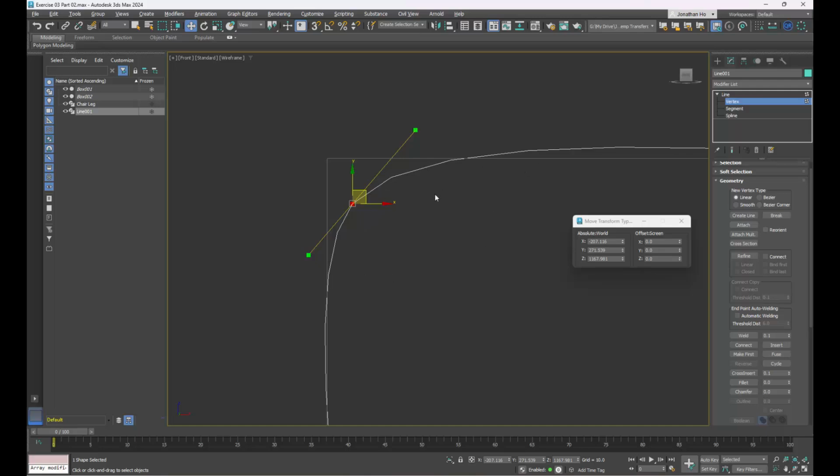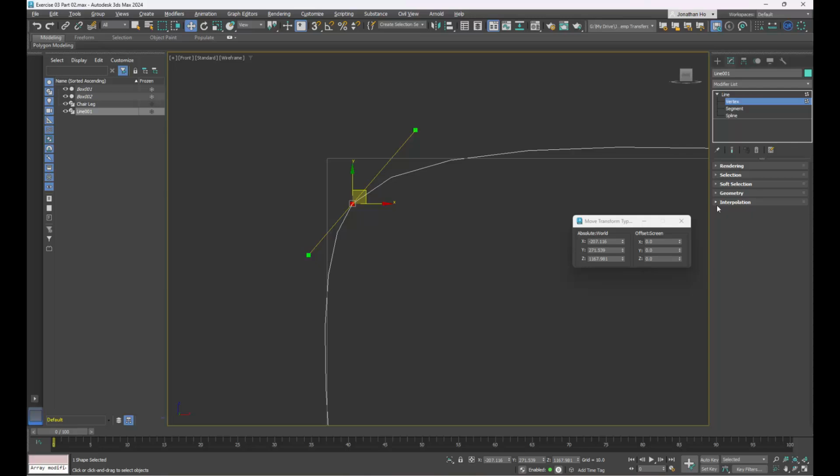It's very jagged because under the interpolation header here, it is set to 6 by default at the moment. So if I increase the number to, let's say, 18, then you notice now the curve becomes very curvy, and it doesn't look very rough and angular now. Okay, this one like that. So we can make this guy really curvy this way.